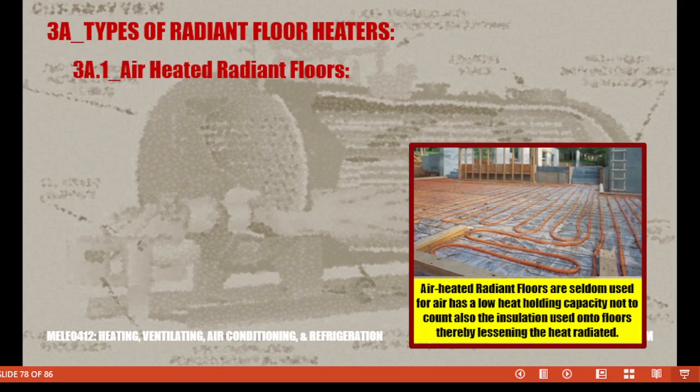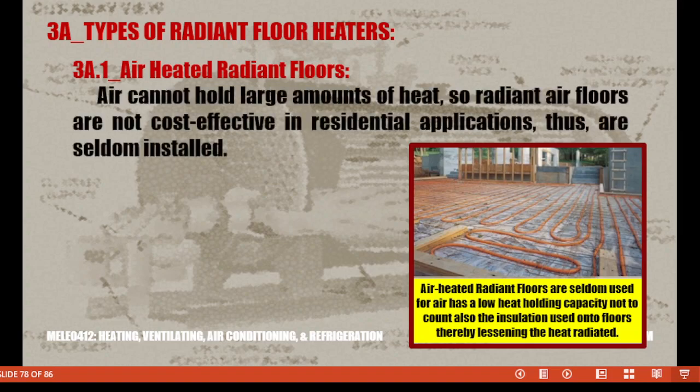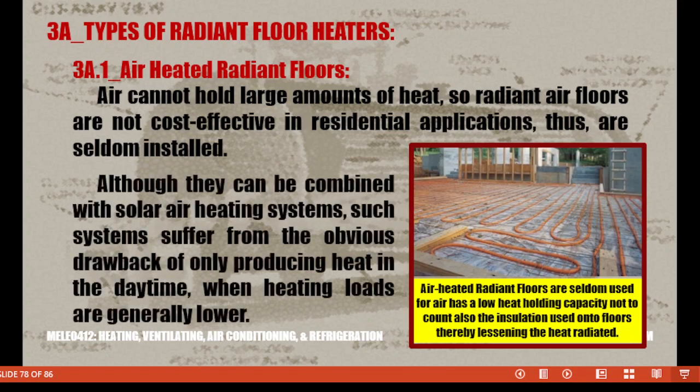So, it uses a system of tubes, pipes, or heating elements underneath such floors. Let us first take the heated air floors, or air-heated radiant floors. Heated air floors are somehow inefficient and thus are not very much considered nowadays. What is the reason? This is due to the air's inability to absorb as much heat unlike water.